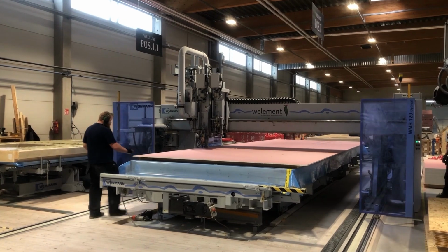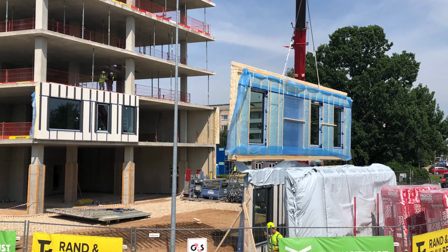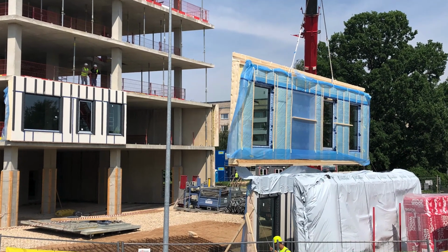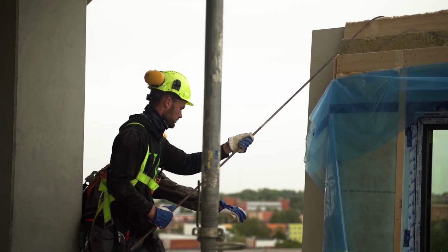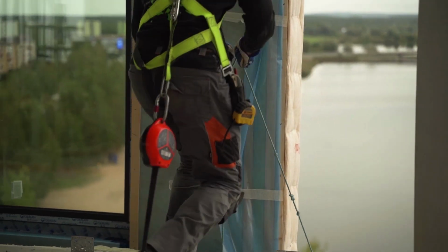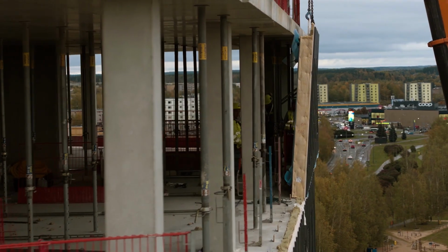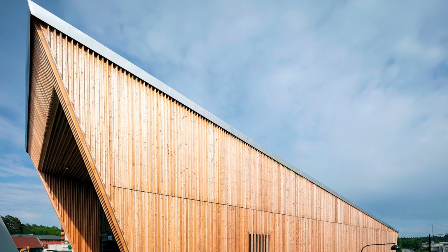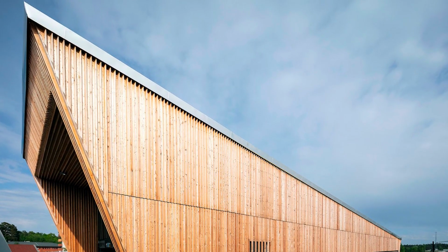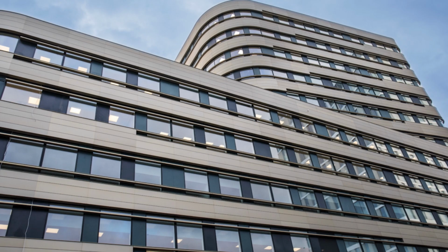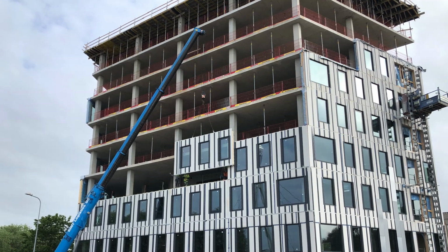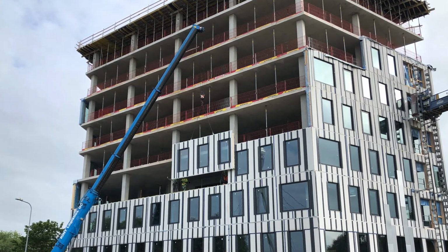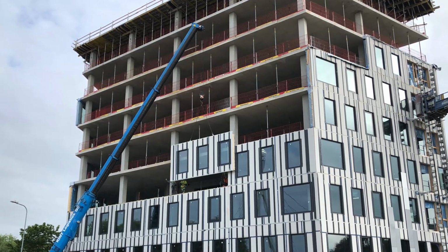The interior surface may have pre-installed plasterboard, while due to technical nuances or to prevent possible moisture damage, a solution is also used where the room-side plasterboard is installed on site after the installation of the elements. The element can be covered with various materials on the outside, such as timber boards, cement fiber board, metal cassette, or other facade covering. Technologically, joints remain between the elements, which must be covered with the prescribed covering material.